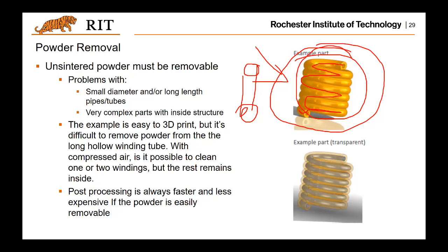So that reminds you that you have to consider this for different processes. For selective laser sintering, you need to consider the powder removal. For stereolithography, you need to consider the liquid resin removal. Different processes, but a similar consideration you need to have.